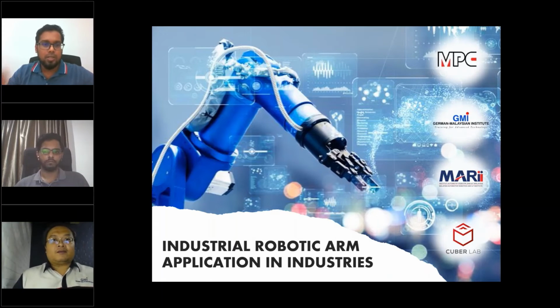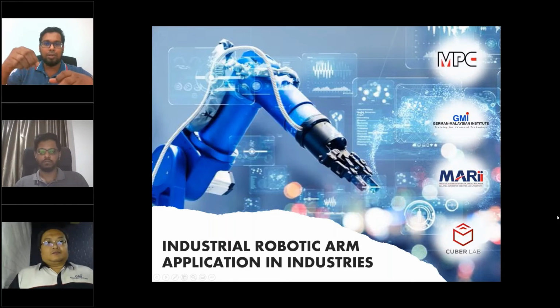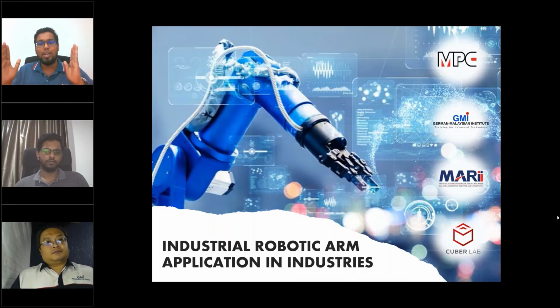Right. So in industry, some applications need you to work alongside humans. Not most, but currently we are engaging a lot more applications for the robot to work with humans. Let's say a human will do some assemblies with the parts alongside the robot that will assemble something really niche or high accuracy. By that time, you don't need to separate the robot application and the human. You can just put a human on one side and the robot on the opposite, and it will work alongside the human. So that's where this collaborative robot is applicable. According to the guideline, you have phases from level 1 until level 5, for how much is the integration with the robot. So we have to go through that to implement this.